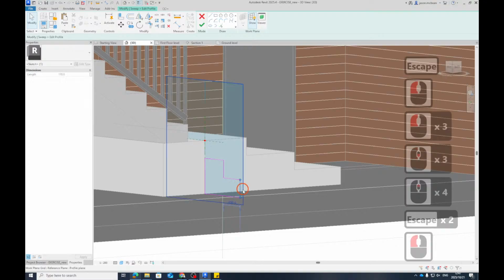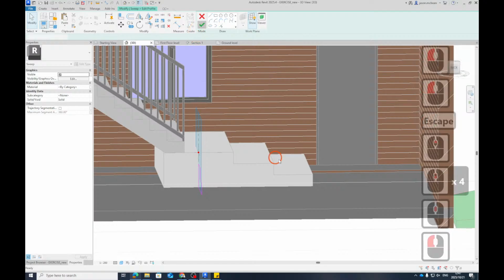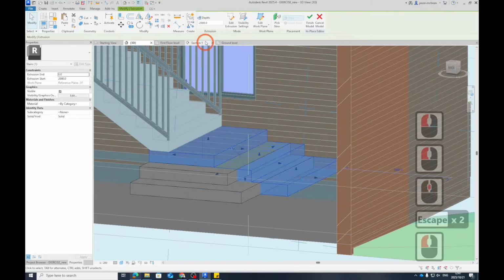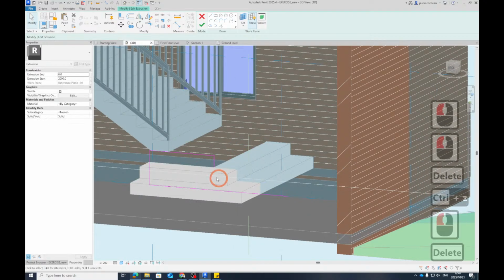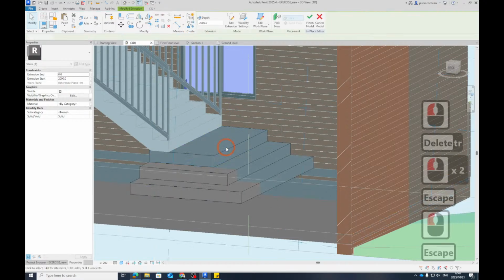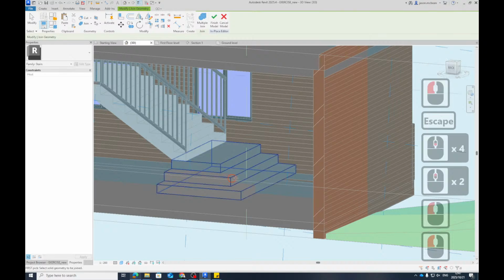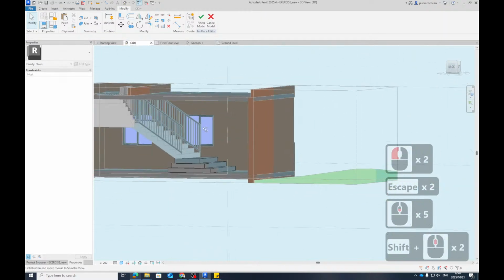Move this there. Now, these landings I can play around a bit. I can make these all different sizes. So watch what happens now. See what it's done. Oh. This extrusion, you still need, I'll explain why you need the one. I don't need these anymore. I don't need those anymore, but I can trim this. Because these two will have to work together, and then you can join them together and they become one object. So some things you have to, see now I've got this nice cool stair that does that.